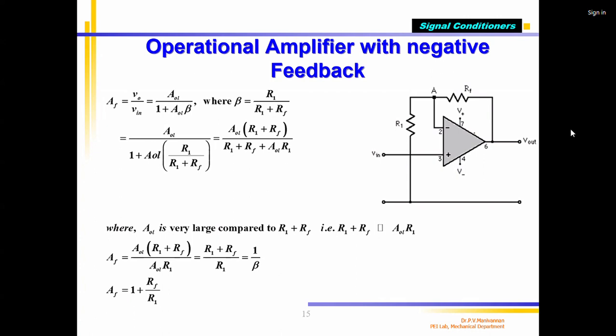So this is the operation amplifier. You can take any operation amplifier. I'm taking 741. It has 5 pins that are important; the remaining 3 pins I am now ignoring. V plus supply is pin number 7, V minus supply is pin number 4, pin number 6 is output, pin number 2 is the inverting input marked as minus, and pin number 3 is the non-inverting input marked as plus. Please see that now I additionally have 2 resistors. These are the externals I'm using. This is my IC 741. I bought it. Apart from that, I used the power supply and gave the input signal. That's it.